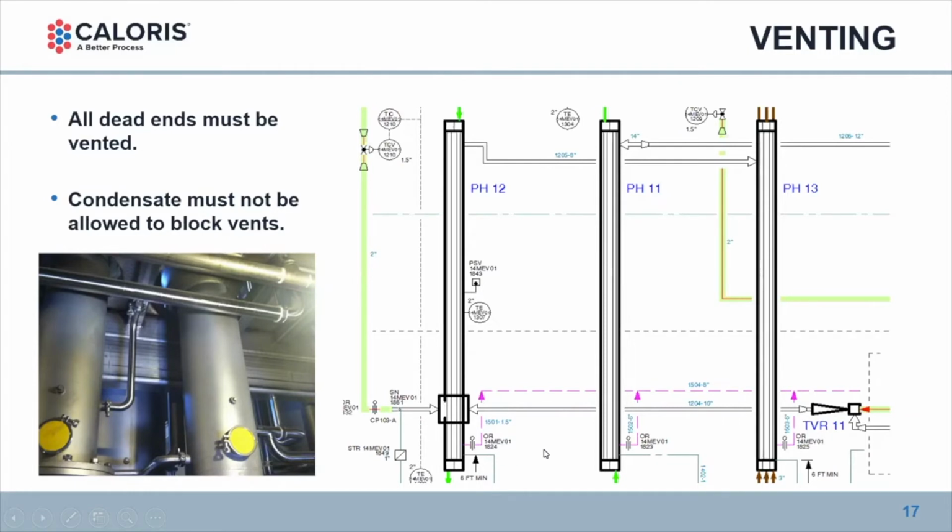And what I'm showing here is with the orifice. That's the most common way that when we commission an evaporator, we select the proper size orifice hole in order to allow a certain portion of the steam as well as non-condensable gases to routinely vent out of the heat exchanger all the time. It can be done with a valve. However, a valve can be adjusted. And what we find is that when we put an orifice in there and we fix it, it stays and is consistently reproducible on its performance for years to come.